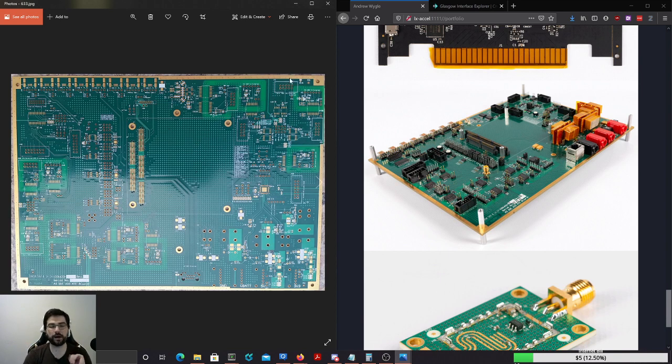But what it's there for is to keep the mass of that layer relatively constant across the board. Because if you have a ton of copper over here and no copper over here, then when you heat it up and cool it down, the copper heats and cools faster than the insulator material does, and so the board will warp because the copper dimensions will change and they won't change uniformly across the length. And so it will apply a bending moment and bend the board basically, or twist it, or just distort it generally. So you add useless copper. I mean, the fab does this, you don't do it yourself, but useless copper is added to keep that mass the same so that you don't get those distortions.